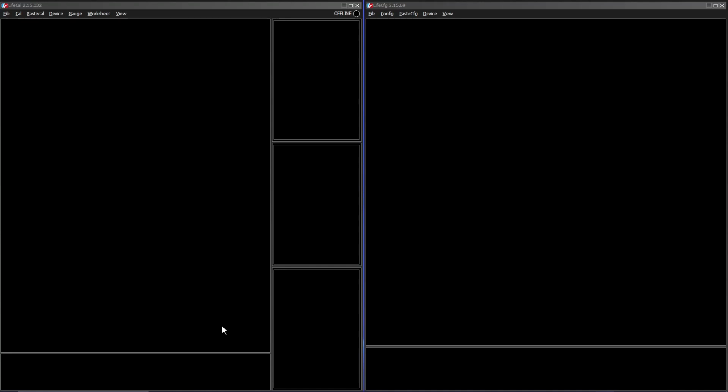I'm just going to show you how to reset the ECU for the calibration for the new engine coolant pressure sensor that we need to set up. We've also got to reassign the I/O, so we're going to disconnect the two dampers for the rear, and we're going to reassign one of the two analog inputs that's then free to the engine coolant pressure sensor.